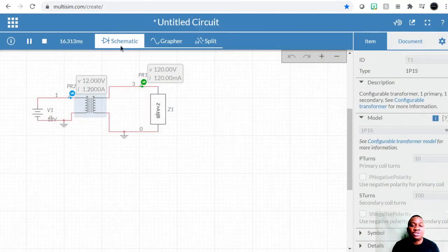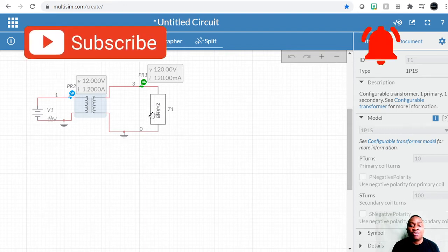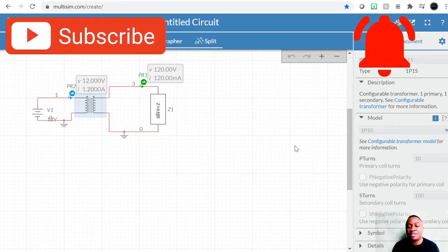All right, so you can see what I mean. But then the current is 10 times less, right? Just makes sense. Power is conserved. Whatever power you put in, I squared R component of your input is also going to be your I squared R component of your output. And this Z is equal to A plus jB, which will be your impedance. Most practical loads we have the real parts and the complex parts.